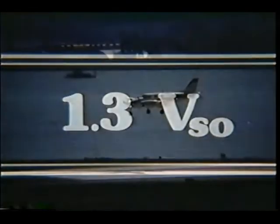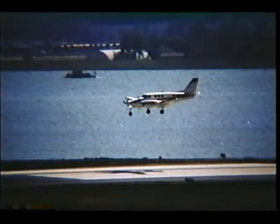Now, we've said that if the manufacturer's recommended final approach speed is not available, use 1.3 VSO. We can think of only 3 instances where this rule is not valid. So before going on, let me tell you what they are. The first is when you're flying a twin. Then you should be at the manufacturer's recommended final approach speed, or if you don't have that speed available, VYSE, the best single-engine rate of climb airspeed, a value which may be greater than 1.3 VSO.